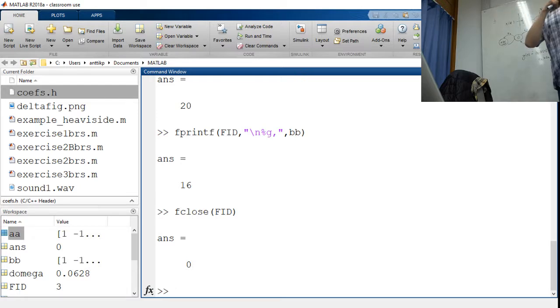So if you are running low on resources, analyzing every single time step one by one would destroy the pipelining of those tasks. It would be more efficient to wait for enough samples and then do block processing of those samples. Then these DSP operations would be done in a nice pipelined way.